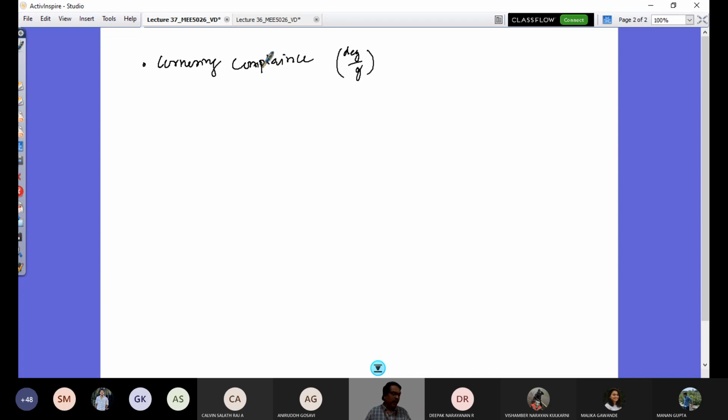Now the vehicle mass is discretized because of the suspension taken into account as unsprung mass and sprung mass. So unsprung mass are the mass that include all the masses of the elements of wheels, axle, anything below the suspension available in the vehicle. Anything above the suspension, your vehicle body and all inclusive of vehicle body, all are called sprung mass.